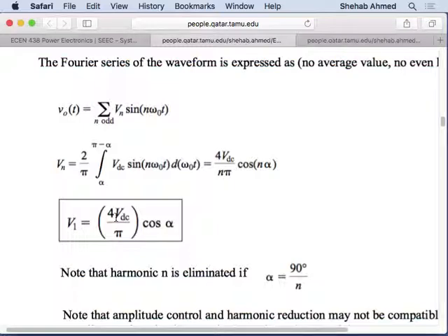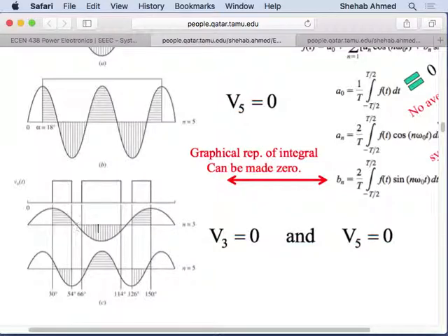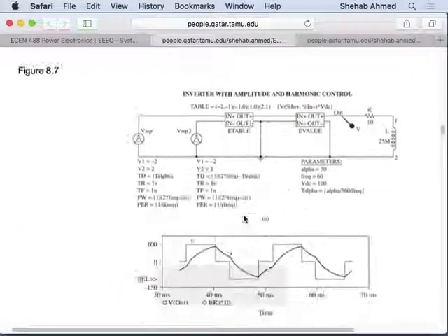They are working on modulation schemes to reduce harmonic content, like we did here, as well as maintain a large fundamental value. People are working on modulation schemes and converter topologies that allow you to do that. So we'll stop here. I think the message is now clear what we want to do next: look at modulation schemes and converters that will help us bring the waveform closer to a sine, eliminating harmonic content while trying not to affect the fundamental component RMS value. Next time we'll address that.